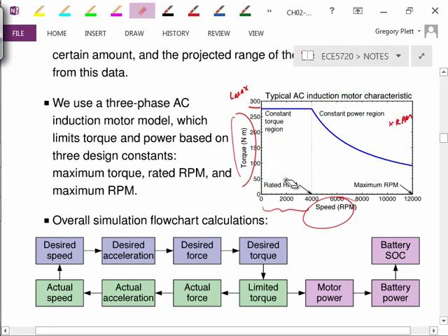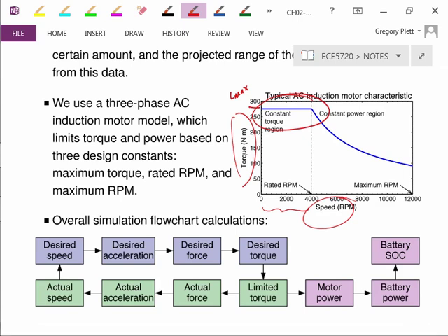For the electric motor we can have a lower equivalent powered motor and we have all of the torque available from 0. In fact, even for a relatively small electric motor, you're probably going to need some kind of traction control on it so your wheels don't slip when you floor the accelerator pedal at 0 RPM. So electric vehicles, if properly designed, now not all of them are, but if properly designed, can be really exciting to drive, a lot of fun.